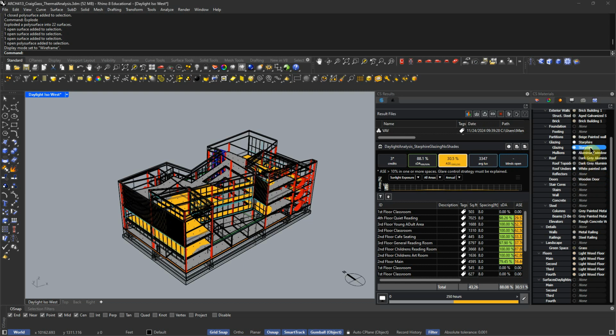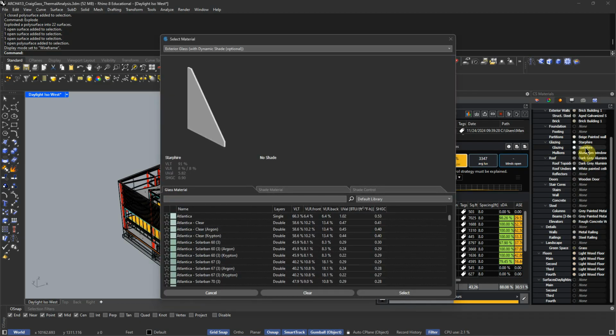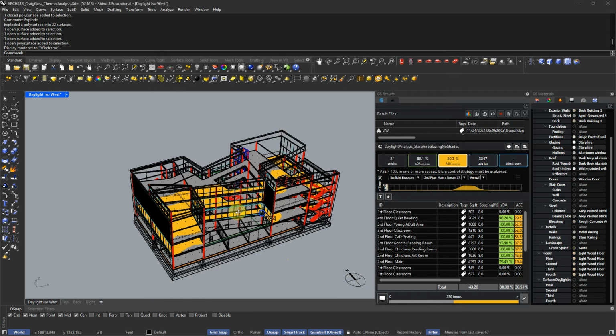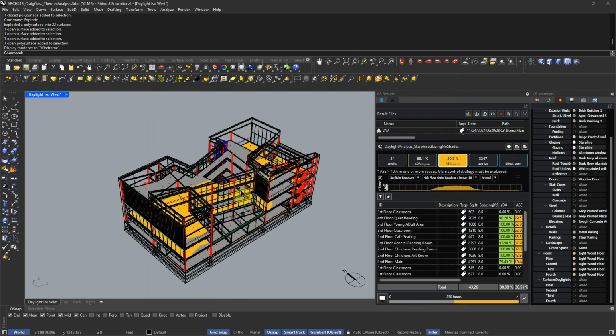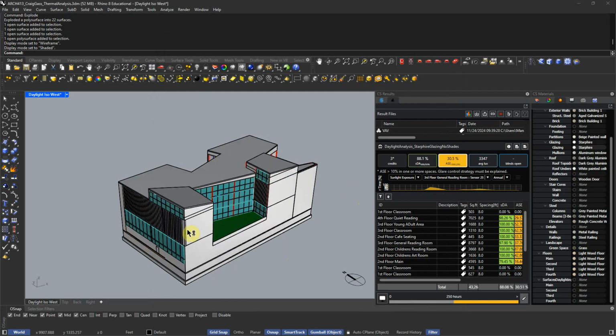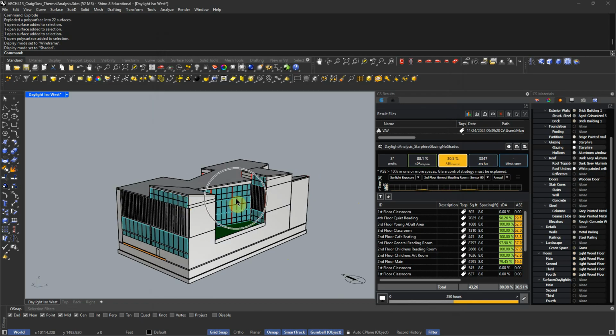Sorry, yeah. Looks like you've got one layer of Windows. By the way, this Starfire on the main layer, unless there's actually stuff on that layer, doesn't matter. You can take that out. But yeah, so this has a visible transmittance of 91%. So we could definitely play with that, and that's one reason why you would probably want to split up your glazing into different layers so that you can put a different glazing on the west side than on the south side.